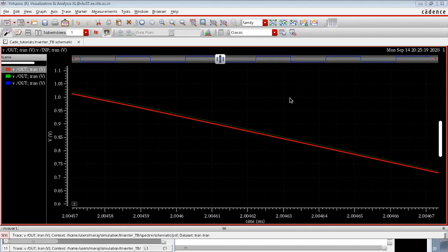You do first schematic simulation, and when everything meets, you just then go to layout and then send it to fabrication, and then you will get your chip back. So it will be, yes, first schematic then layout. That will be the thing, and before sending to fab you need to do all those PVT analysis. So, have I cleared it?